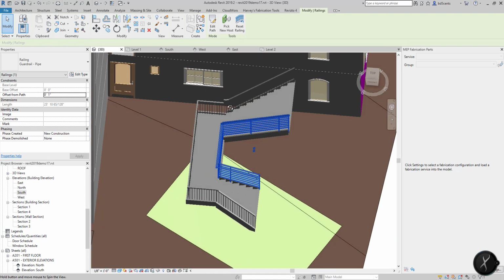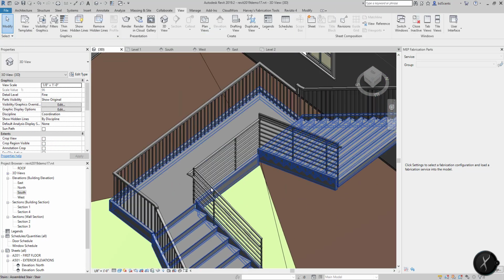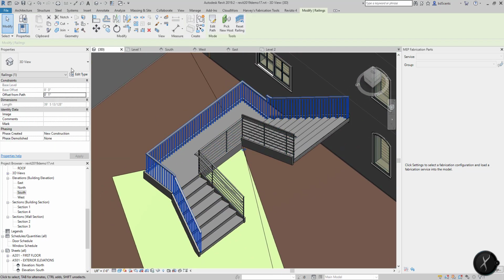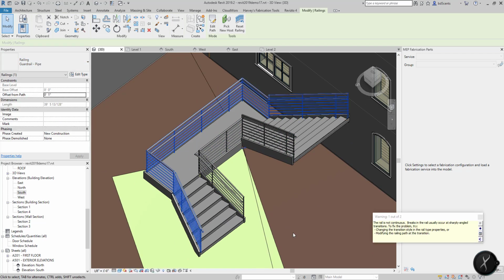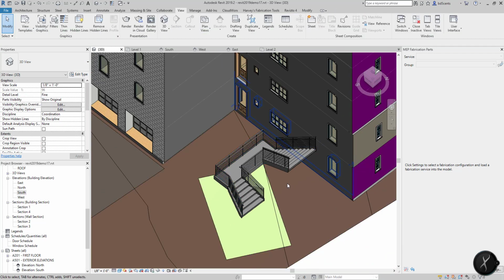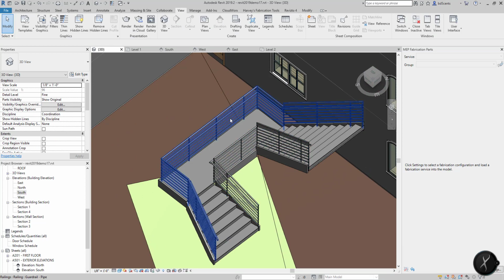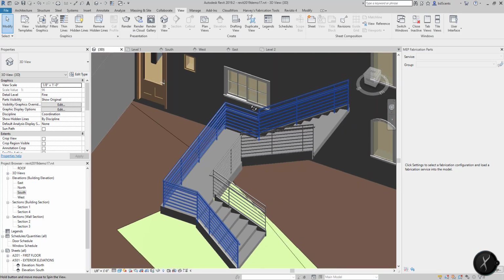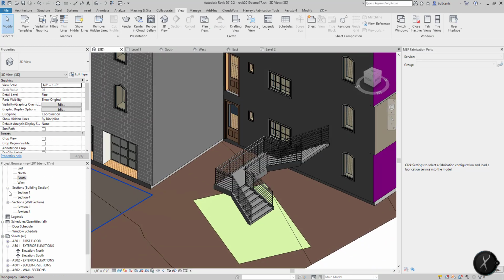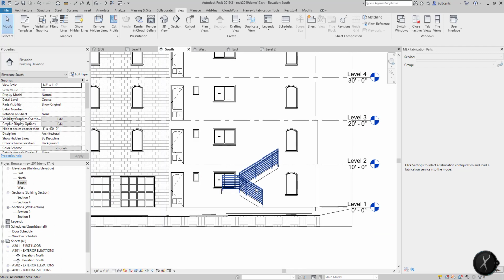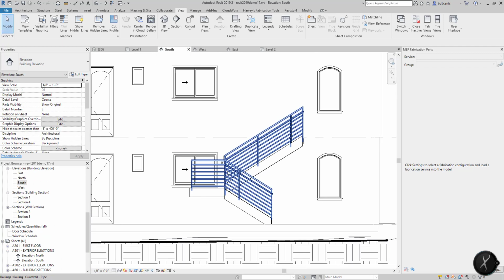And that's okay, because it looks like it's drawing it actually correctly. And then I'll adjust this one to also be that pipe guardrail. Same thing, there's a warning, but that's fine, because it's actually drawing it correctly, so I'm not going to worry about it. And you'll notice that those as well, because of Revit being the database, are updating those views.